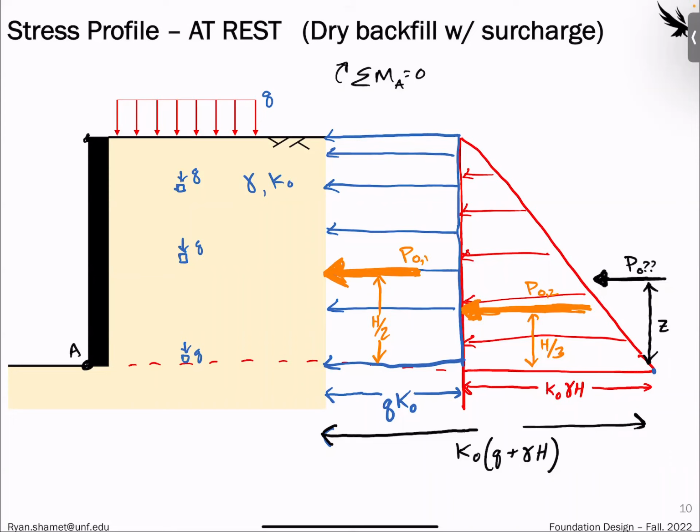So oftentimes in geotech there are going to be different layers. So knowing how to do this for different layers, you might have more than just 2 horizontal earth forces. So we can find the overall P naught by just adding these 2 different ones, P1 plus P2. That's why sometimes you'll see these, especially if it's surcharged, you just add the 2 together.